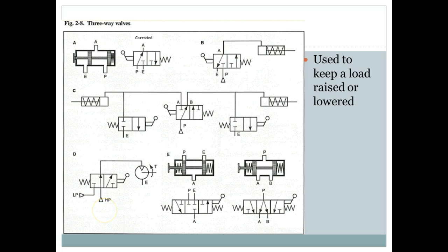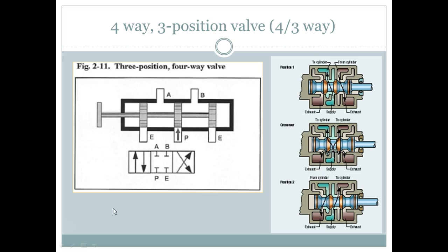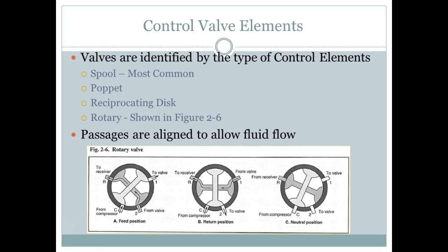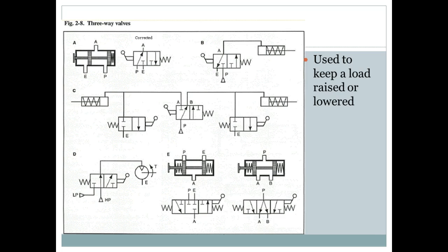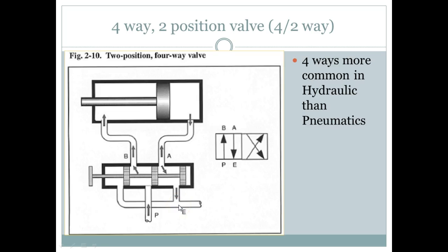And that would be on a 3-position valve. Of course, we also call those ways. That would have been another good question too: what's another name for ports? We call them ways, right? So we have a minimum of 2, a maximum of 5 on our ports. We have 5, with 2 exhaust ports.